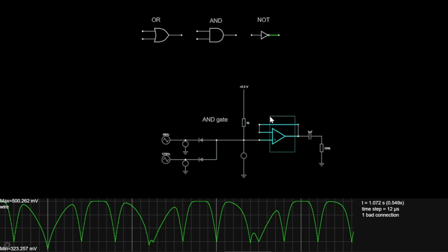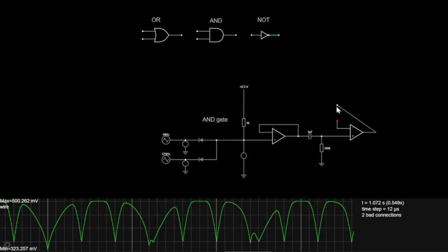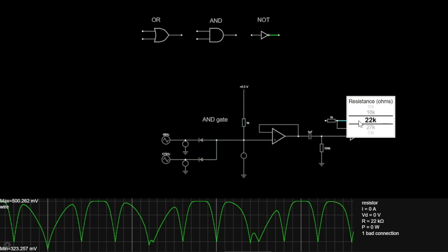Actually, it's either this or you put a filter on the square waves instead. But this is one idea that I will go with in this project. So we have to amplify it now. So how large is it? It's sort of 150 milli. So we sort of have to amplify it 80 times or something like that. Ridiculously a lot. But that's quite simple to do.